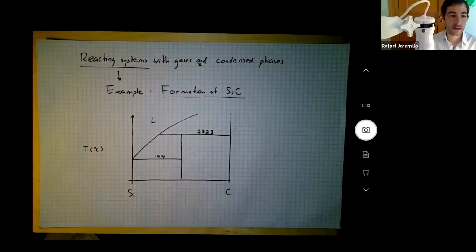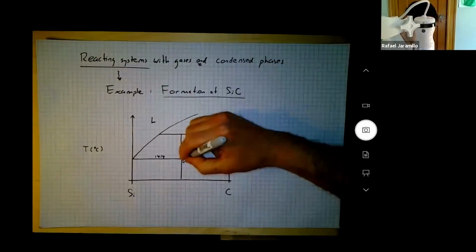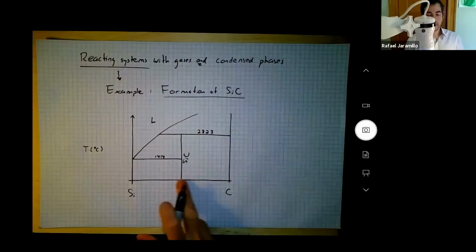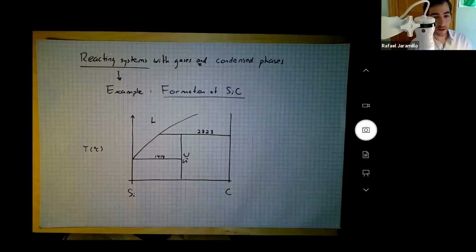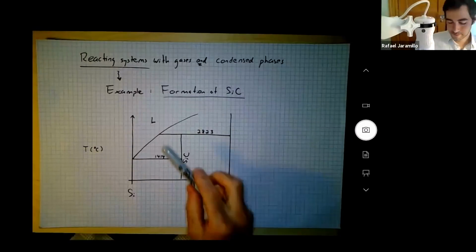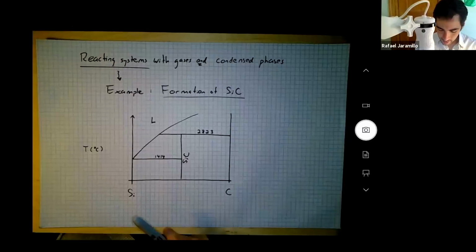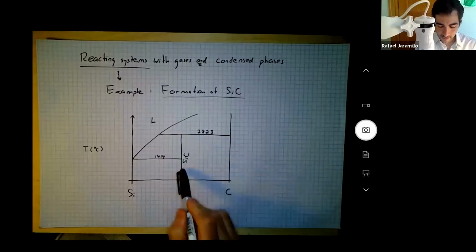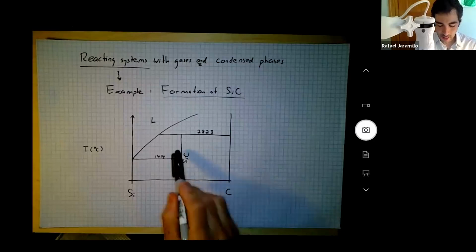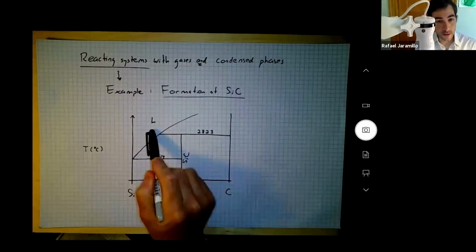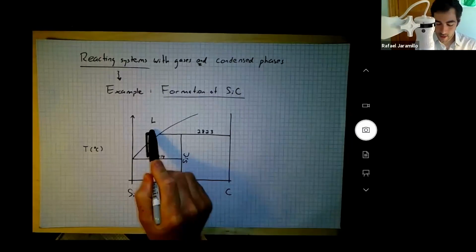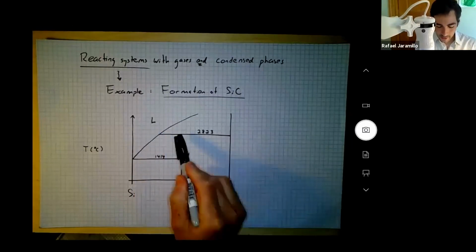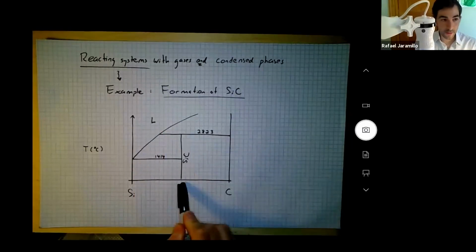So silicon, silicon carbide, and carbon, right? So three solid phases, and one liquid phase. And all right, so here's a peritectic reaction, right? This is a peritectic reaction. It has a T shape. It's a liquid silicon-carbon containing melt and graphite reacting to form silicon carbide. So silicon carbide forms out of a peritectic.